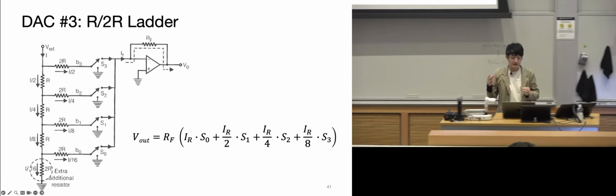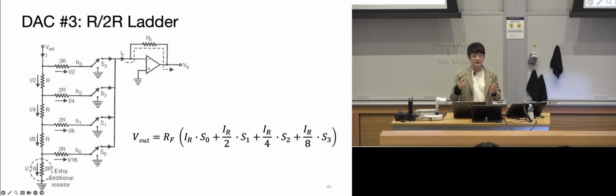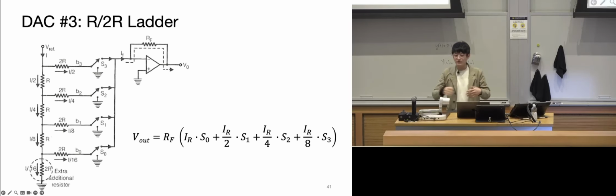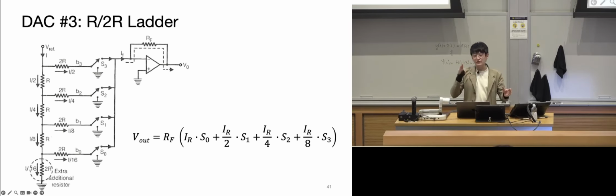From a fabrication and manufacturing perspective, it's much easier to do an R, 2R, 4R, etc., rather than an R and then a 2.2R or 4.7R, etc. It's a similar idea. It's essentially a fancier voltage divider and uses fewer resistors.